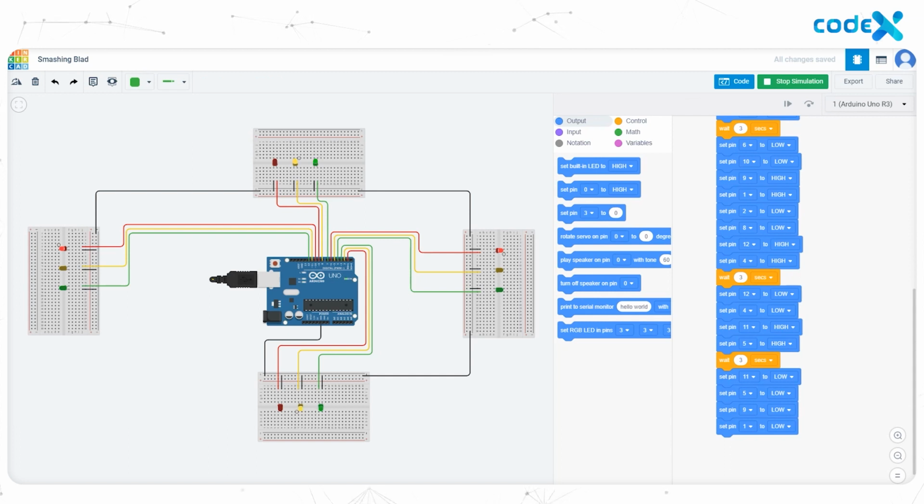Now what if any vehicle is in the middle of the junction when we block road 1 and 2 and allow traffic through the road 3 and 4? Or vice versa? There may be a chance of accidents, right? So for extra safety, we need to add a delay between red signals and green signals. That is, whenever red signals are turned on, traffic through the other roads will be allowed only after a delay.